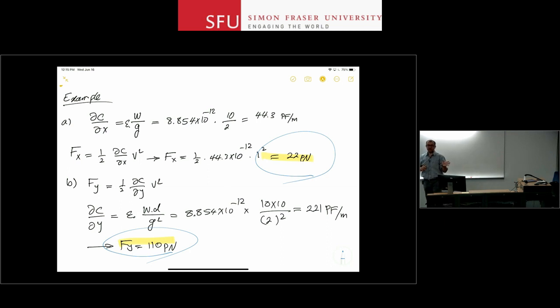For the sensing side, that's also helpful, because remember, the sensing side was also proportional to dC over dx or dC over dy parts, right? So in the MEMS industry or microsystem industry, there has been a lot of effort towards making these gaps as small as you can.